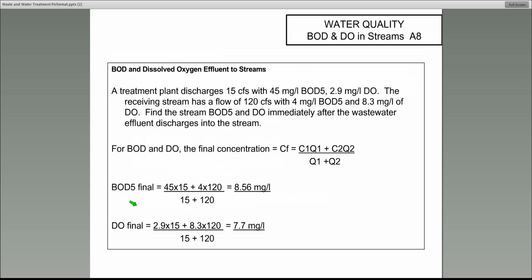Okay, to calculate how that wastewater treatment plant would affect the stream right after it hits the stream, not a 7-day DO sag curve, but to use the dilution formula. It's basically the plant discharge, Q, 15 CFS, and 45 BOD. Plug that into that formula, C1, and then the stream has BOD of 4. That's from the fish and the dying bacteria in the stream.